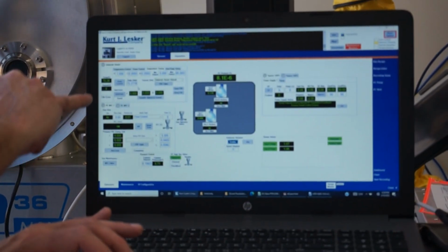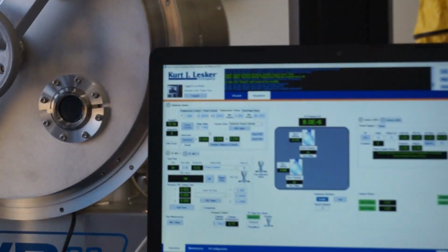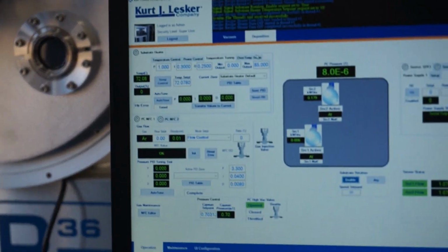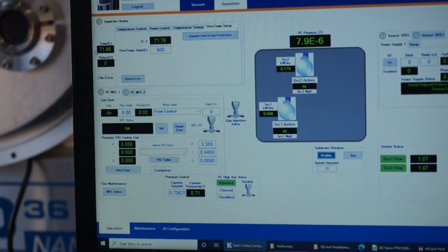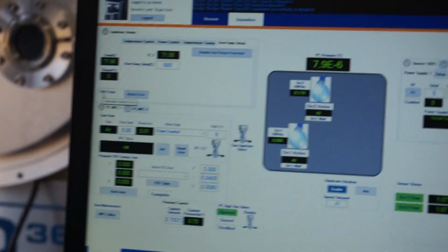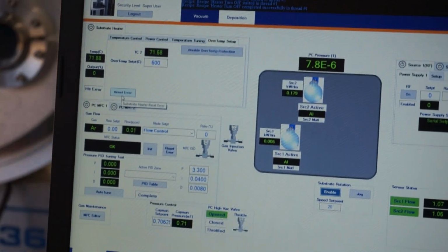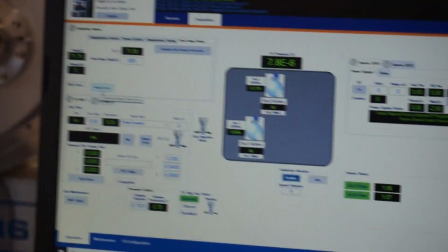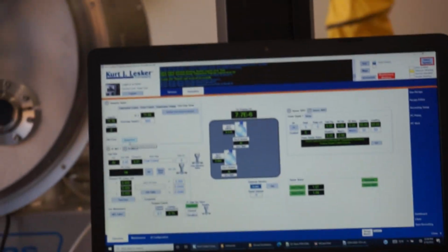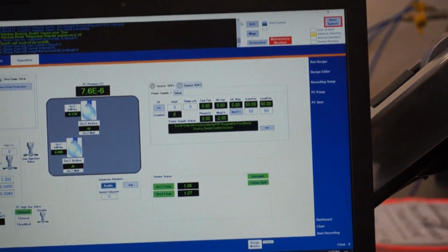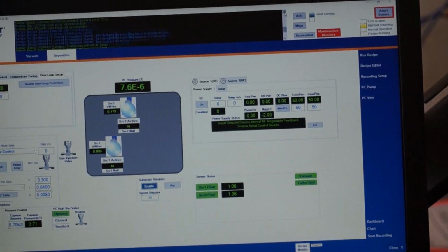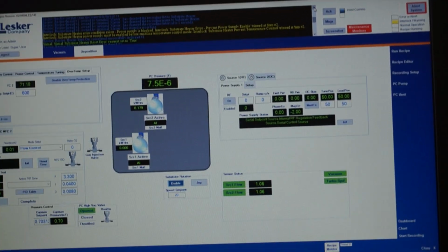You mentioned earlier that this was checked here, that default, or the heater error in red. Whenever I hit the EMO, I think that's what might have triggered it. So I just hit this reset error, and that's what changed the state from red to white. Because when I tried to run that, I still had that at the error, and it prevented the heater from turning on. So somewhere up here, yeah, we got an interlock.